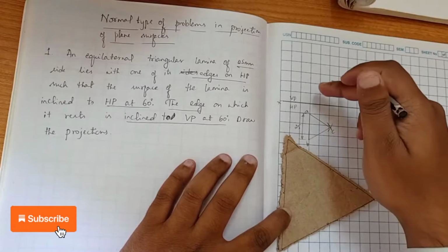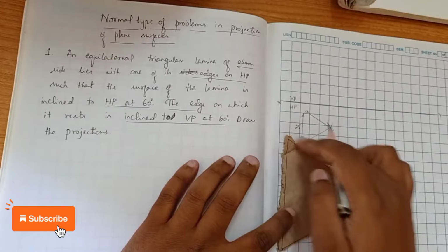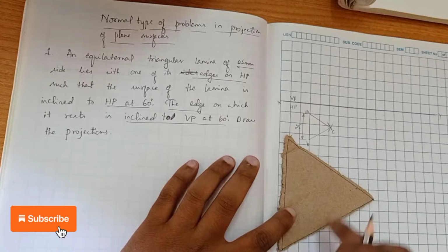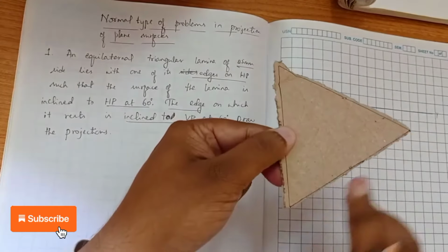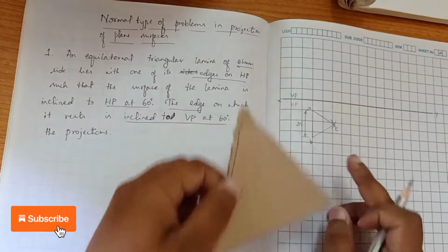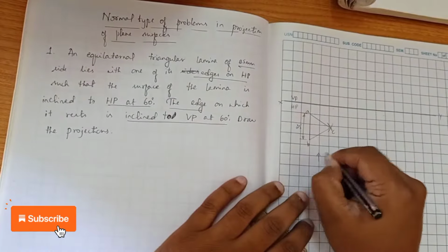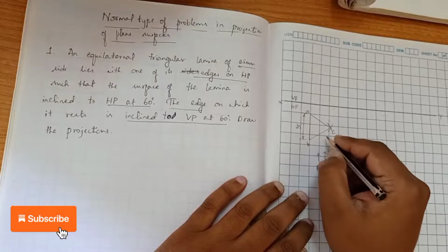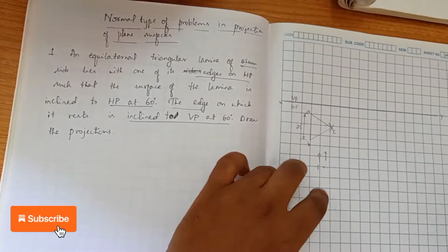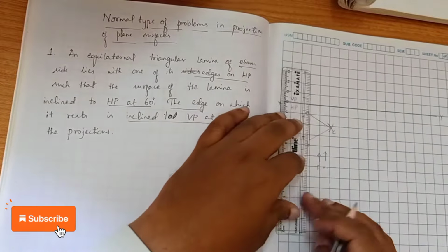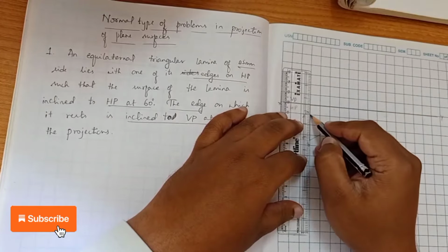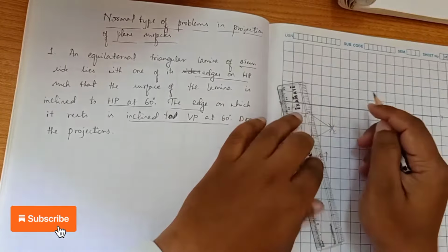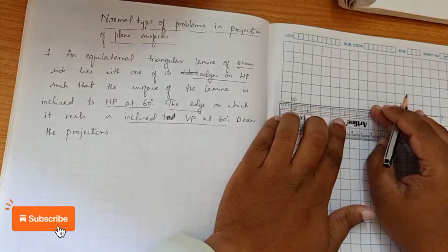So we know that the front view will be lying in the VP plane. In this top view we have got the triangle of dimension 25. If you are looking at this triangle from the front, you are able to see only this edge, that is BC, correct? Only BC. So to project the front view, we will be using the projection line here. The projection line will be a thin line, and then the front view we will get on this XY line here.